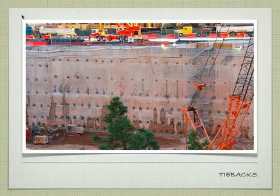How far in do tiebacks go on something big like that? How far do they go back? Could be 50 to 100 feet. Could be less. Depends on the type of soil. That's always the big concern. They have to go far enough back so that the friction along the length of that grouting will hold, and that depends on the type of soil that you're using.